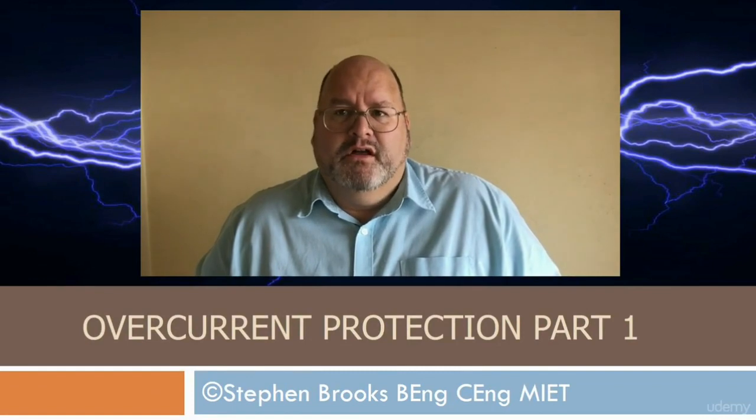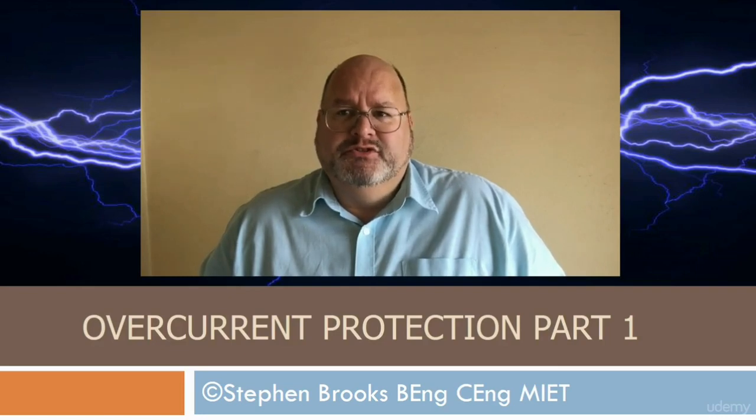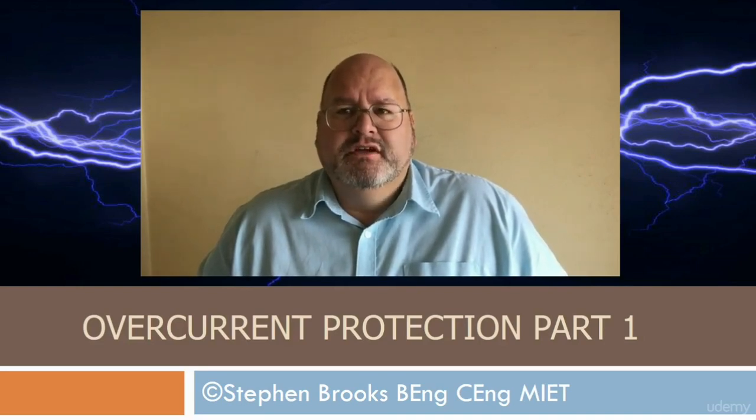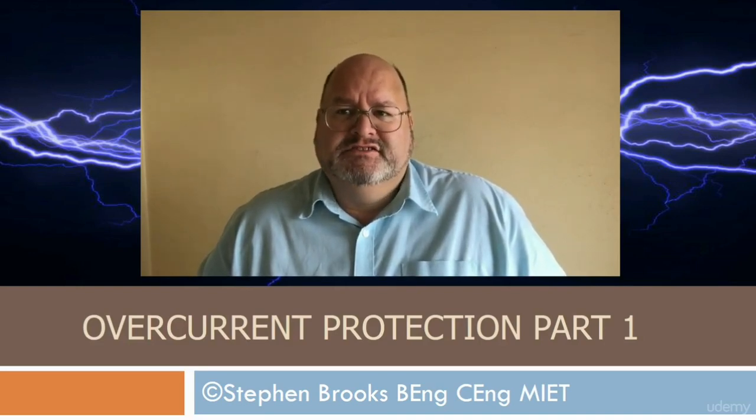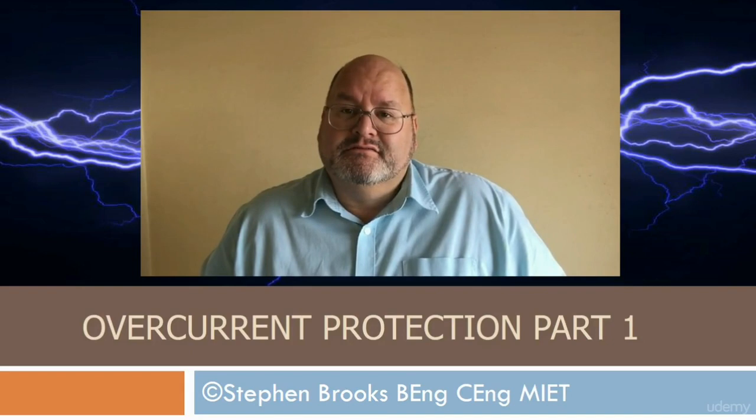Welcome to the first module on overcurrent protection. Overcurrent protection is the most widely used protection device that we use on the distribution and transmission network and appears on the most simple and complicated system. In this module, you will learn the basic principles behind instantaneous overcurrent protection and see how an overcurrent relay is connected to the current transformers that feed it.